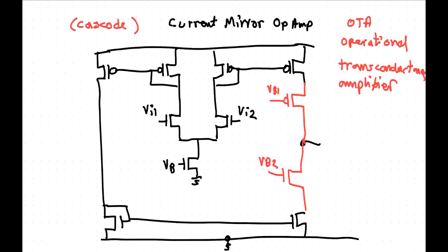So if you look at how we get gain here, we have really taken the difference in current, and that is what is injected into this point here. The difference in current is the transconductance for the differential pair times the input voltage, and you dump this current into the output node. The output node has a very high impedance because you put in the cascode. So now the gain you get from that is gm rds squared or something like that. You should probably work it out.